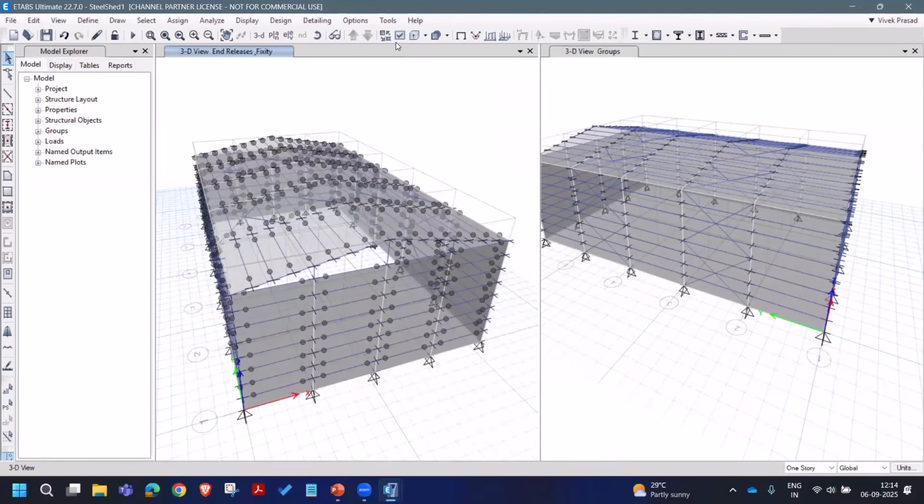Now, one important thing about this cladding is that it will take the wind pressure coefficients as a user input, and the automated wind load will be applied to this. Then it will be transferred to the connected objects, and that should apply the wind force for the analysis. So it is completely automated except for the wind pressure coefficient to be assigned by the user. The program is not automated to calculate these coefficients internally, so from the code, you will have to apply this.